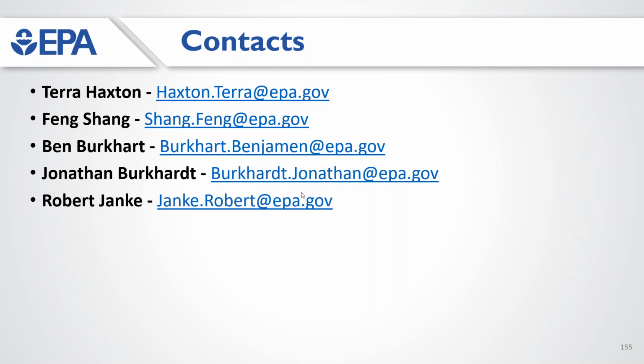Commercial software has a fire flow analysis module, but it's basically using the hydraulic engine of EPANET to run 100 scenarios, simulating a fire flow junction by junction. That's probably most likely what they do. You can do it manually. You can use the EPANET toolkit if you can program to simulate a fire flow node by node.